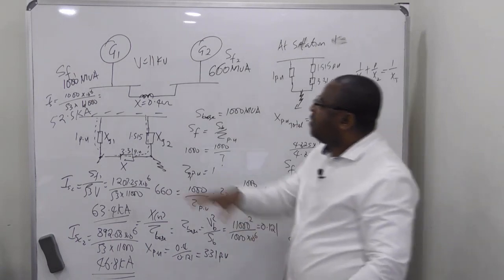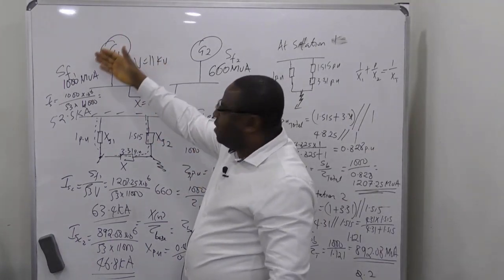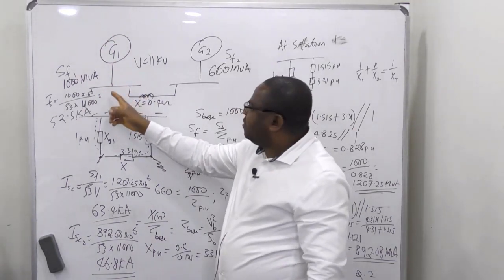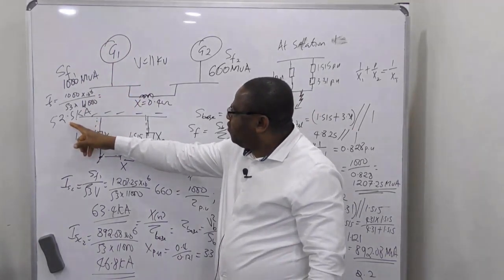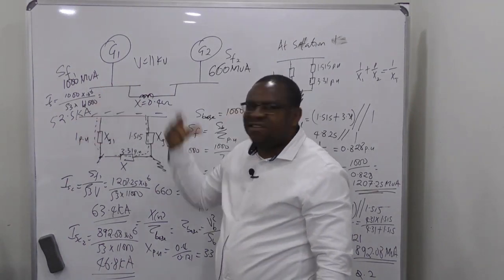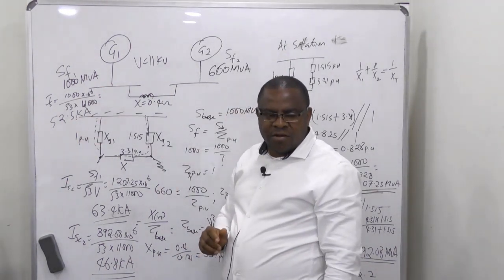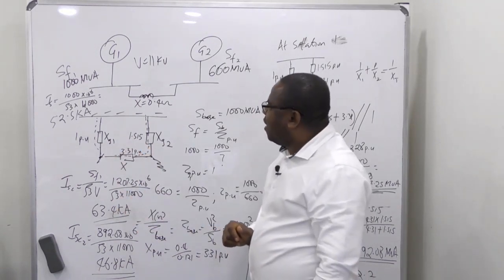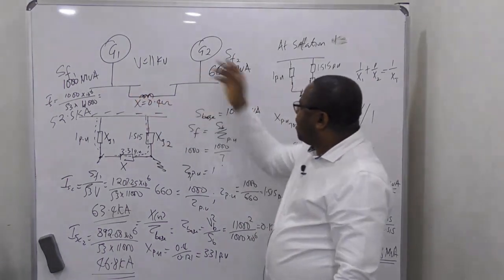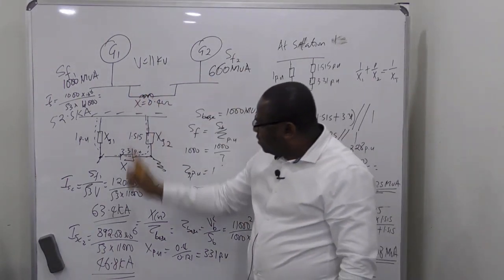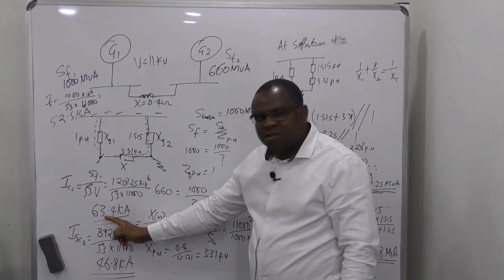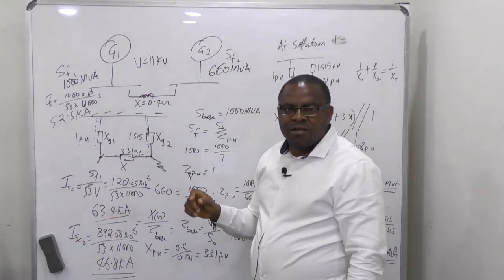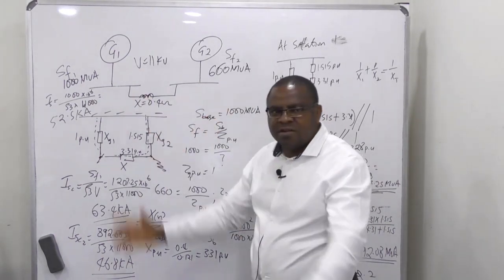Now let's assume that this was not there, and this guy did a design and did his calculation. And from his calculation, he got 52.5 kA and he put a 60 kA board. All right, which is okay. 60 kA board is okay for this installation. And now, we interconnect this with that. Wow. The fault current now increased to 63. And the guy did not change the switch gear. He just interconnected that and said, wow, everything is fine.